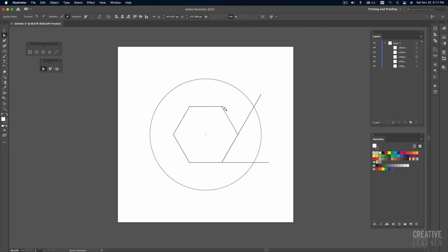I will select the point at the top here. I can simply drag it first outside of this circle, and then snap it to my line. If you're not sure, the Smart Guide helps. We see the pink line extension, and even text appears. Then I let go of my mouse, and boom, we have this. Easily we can build this shape.